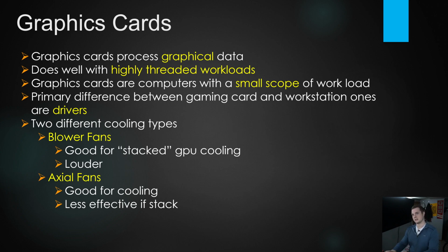The other thing is if you have multiple things in your PCIe lanes and you have something right next to the graphics card and it's an axial fan, it's still not going to get air, and it's not going to work very well. Okay. The other thing you have to be worried about is if you're using a server that is like a 1 or 2U, you might have a hard time fitting that GPU in there, especially if you don't have a riser card. So a few things to be aware of when it comes down to that.